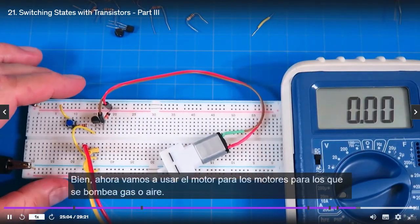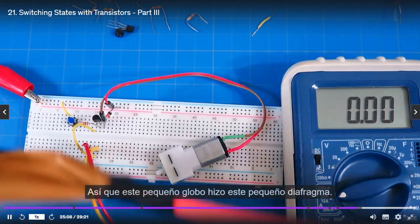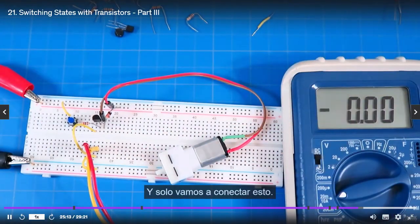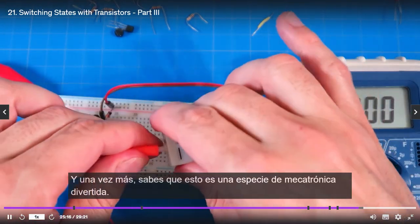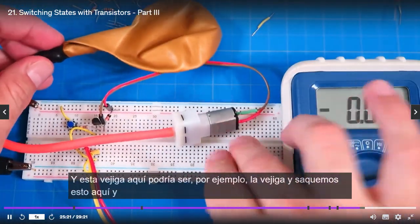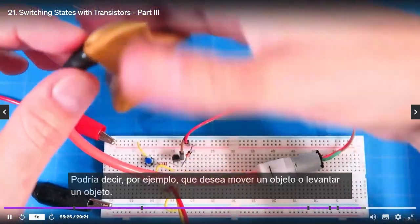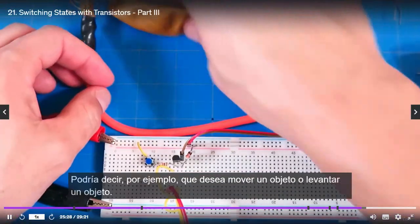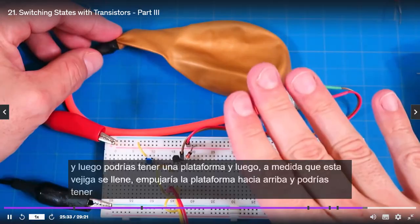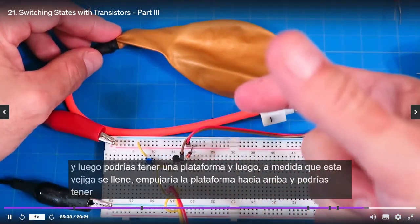Now let's use the motor for what it's for, which is pumping gas or air. I've made this little balloon, this little diaphragm kind of thing, and we're just going to hook this up. This is some fun mechatronic stuff. Say you wanted to move or lift an object. You could have a cylinder with the bladder inside it and a platform, and as the bladder fills up, it would push the platform up, and you could have a spring to pull it back down.